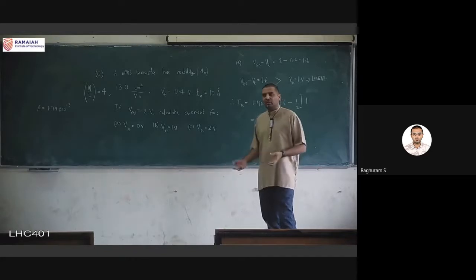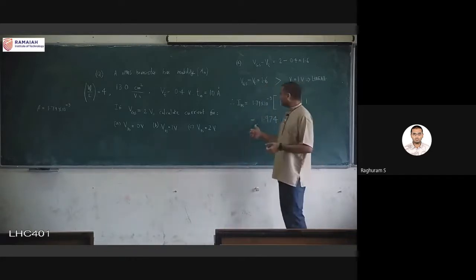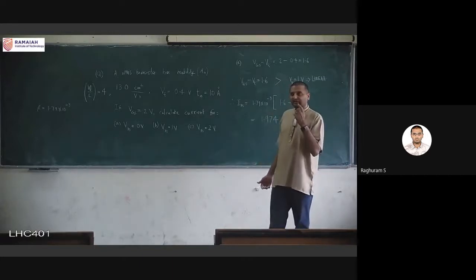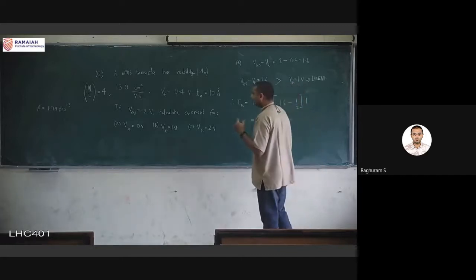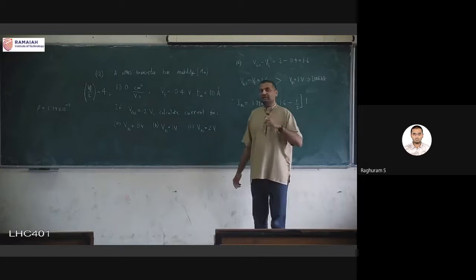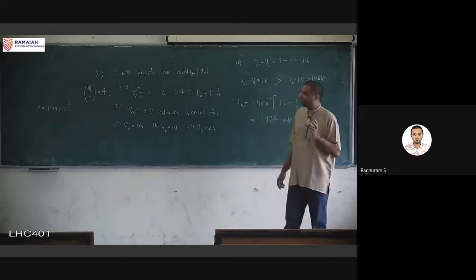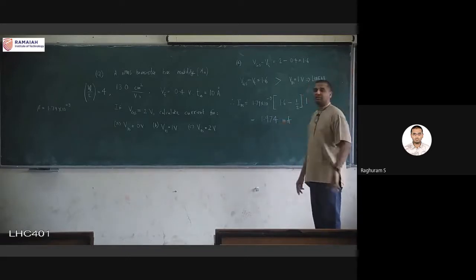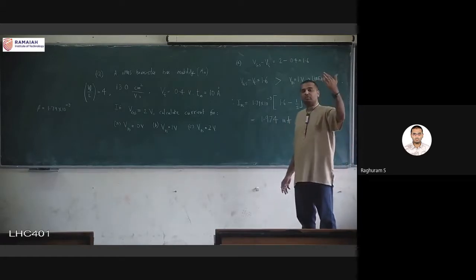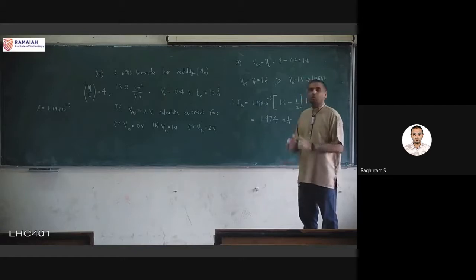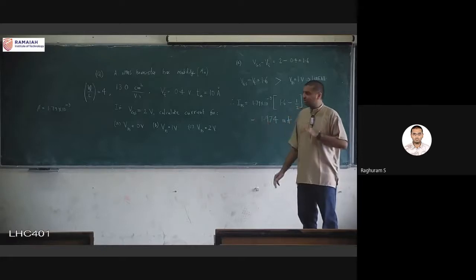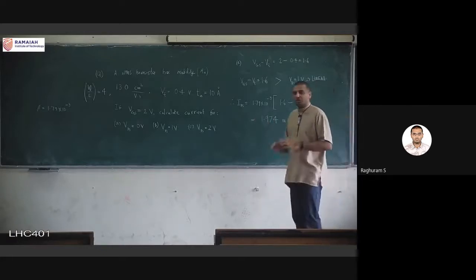So these are what are called physically significant values, and that also means that the numbers that we get for current should be correct. The main reason why things could go wrong is because of the centimeter to meter confusion. If you go in one direction, that is, instead of 1.974 milliampere, you might end up with 100 times more, that is, 0.19 ampere. 0.19 ampere in a single transistor of these sizes will immediately burn the transistor. It's just too high a current, so that's not going to be realistic.